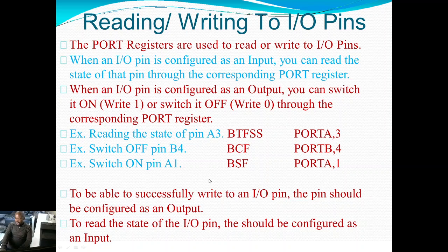Now, to be able to successfully write to an I/O pin, remember, we write to a pin, we switch it on or off. We write to it when it is an output. So to successfully write to a pin, that pin should be configured as an output. If a pin is configured as an input and you write to it, that write is not going to be successful, because the state of that pin is determined by the state of the input. But if that pin is configured as an output, you can successfully write logic 0 or logic 1 to it, because you are allowed to write to it since it's an output.